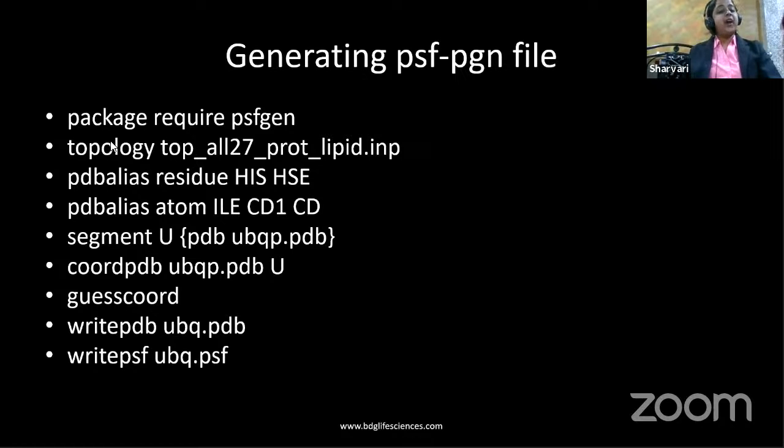Then the next file that we are going to call, as I mentioned to you, is our topology file. So top_all27_prot_lipid input file is the standard file. Then pdbalias residue HIS HSC. What does alias mean? It means instead of. So wherever in the topology file HIS is seen, it will change to HSC. Then alias ILE CD1 CD. So there are certain standard formats of the residues which are accepted by NAMD.